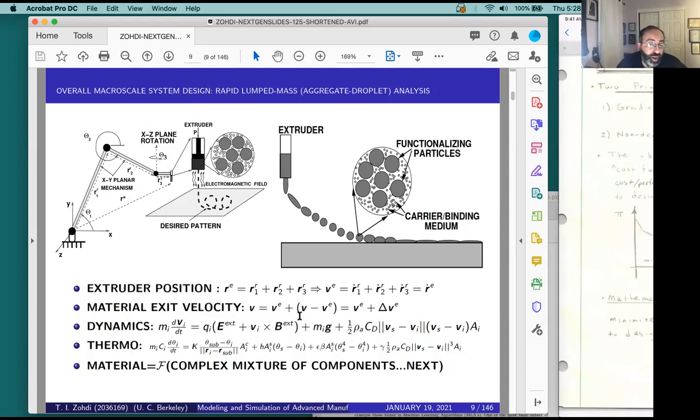You have then the gravity, which is self-evident. That's obvious. Something is getting squirted out. Gravity takes over. And then finally, you also have drag, because there potentially is some kind of fluid in an ambient atmosphere that might be pushing or pulling these particles in the system as it's being deposited. That's very possible, because oftentimes in these kinds of processes, we have cooling fans. So there's definitely going to be some ambient draft that might potentially move things around if we're not careful.